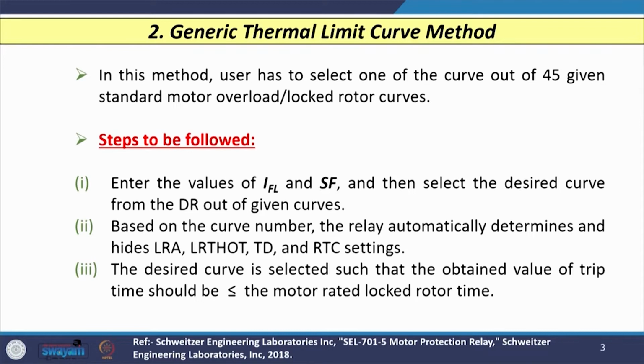So, what are the steps to be followed when we use the generic thermal limit curve method? The first step is that we have to enter the values of the full load current of the motor and the value of SF, that is the service factor, and then select the desired curve from the curves given by the manufacturer. This is the first point we need to consider.